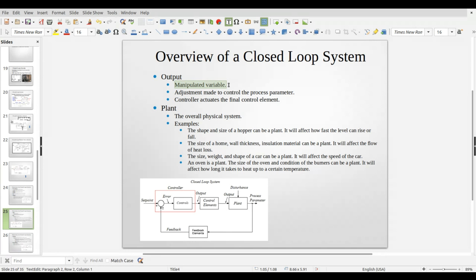All right, and then we're going to generate this output, which is going to come out our analog out. It'll probably be a 4 to 20 milliamp signal. It could be a 0 to 10 volt signal if we want to use a voltage out, but we're going to generate that output signal and then send that into our system.